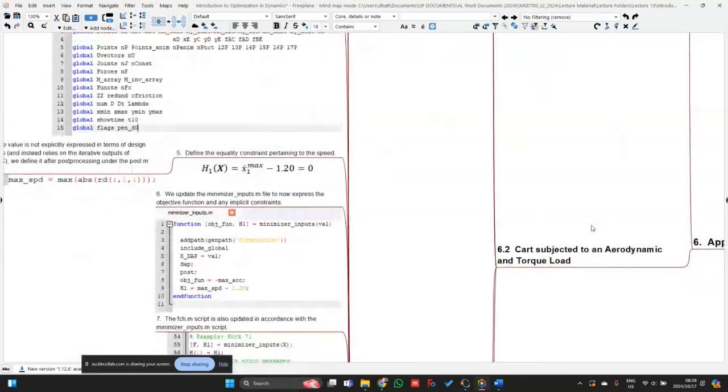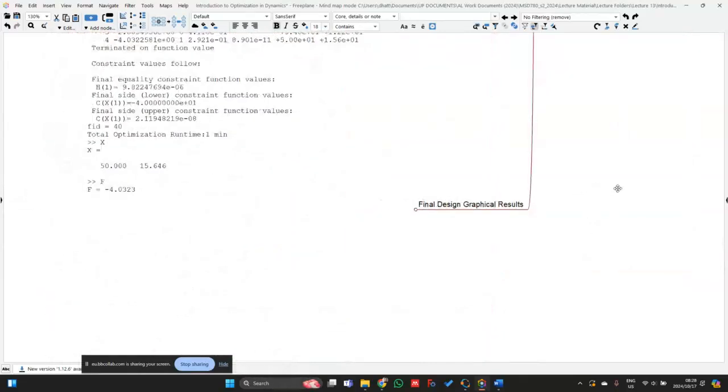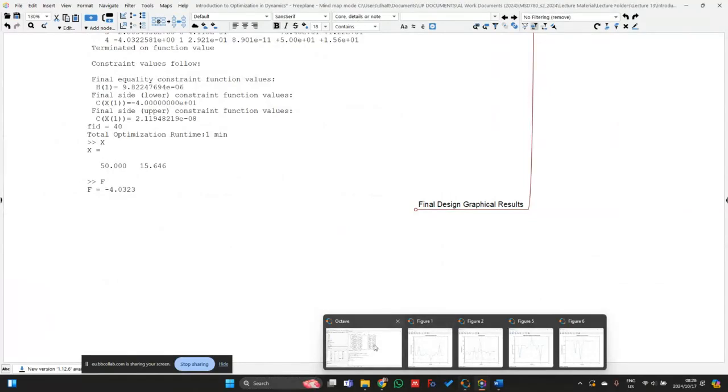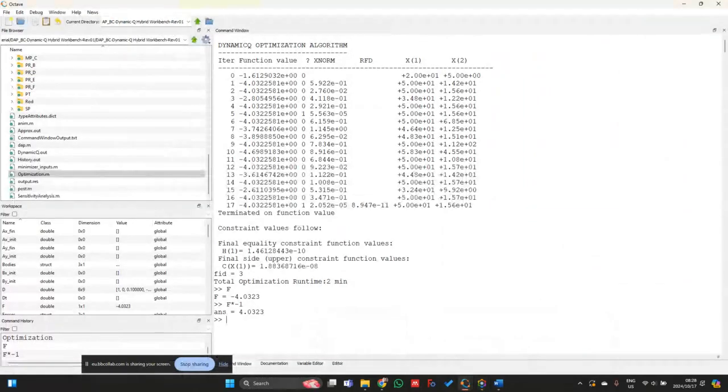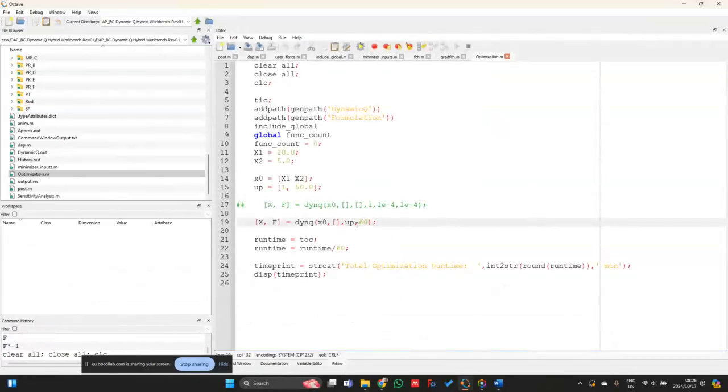All right. So I think that's more or less the results that we wanted to get over here. Let me perhaps just check what would happen if we change the convergence tolerance on the step size. Let's make this one 1e minus 4 and 1e minus 5. So this is just for the x norm and then for the f norm. So we can first see what this one is going to do.